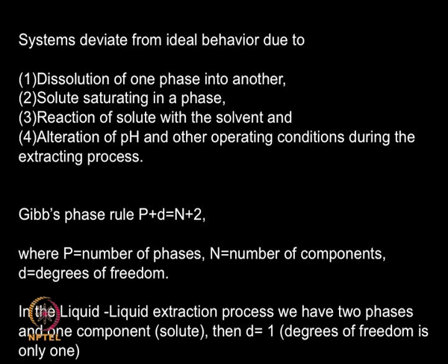So if the concentration of the solute in the solvent phase is known, then automatically the concentration in the fermentation broth or feed is fixed. So there is no extra degree of freedom, there is only 1 degree of freedom for this type of liquid extraction. So you see thermodynamics plays a very important role in this process, and the phase rule determines the number of degrees of freedom present for this extraction process.